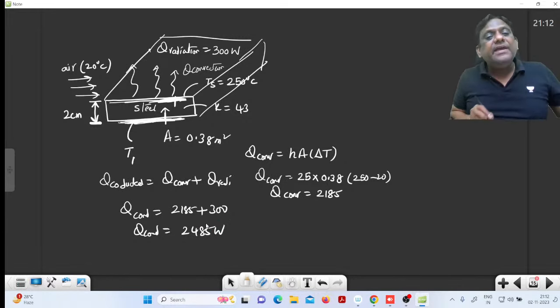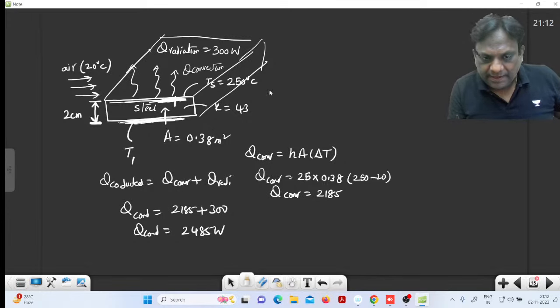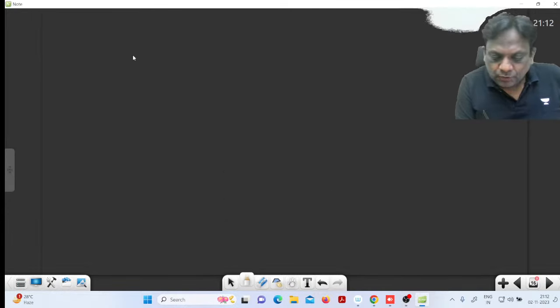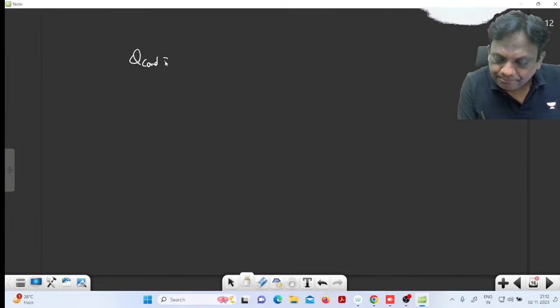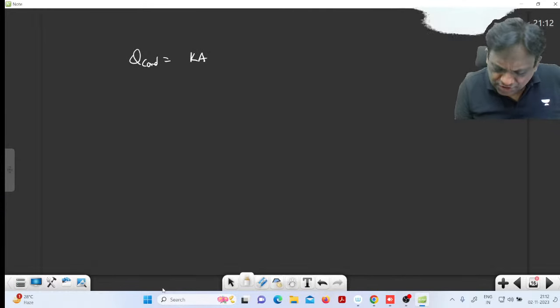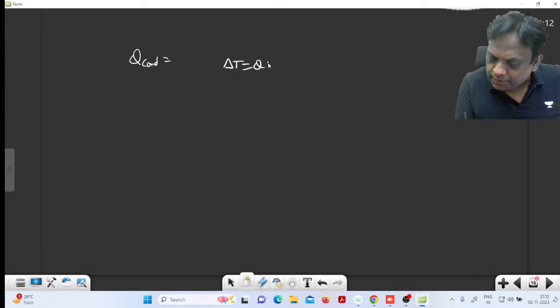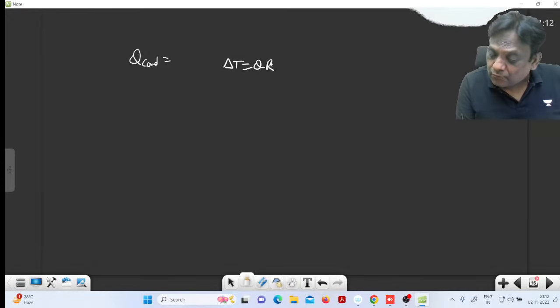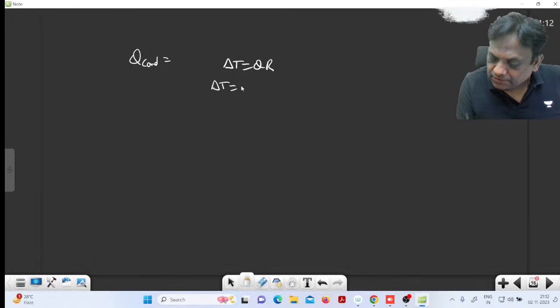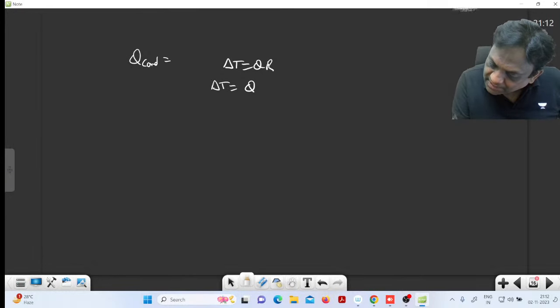Excellent sirs. Now, what is this heat doing, sirs? And you know heat conducted is equal to, my dear students, you know very well, kA del T. I am telling it this way. Delta T is equal to Q into R. Already Q is known. And what is conductive resistance? If this is the heat transfer by conduction, it will be conductive resistance L by kA.